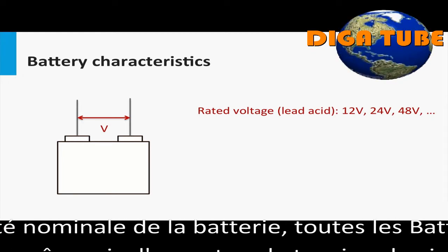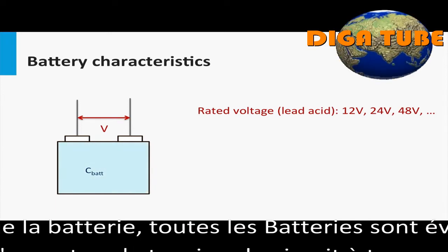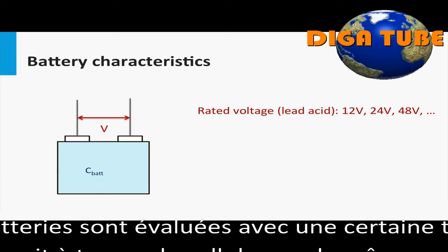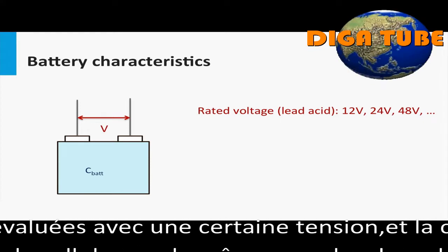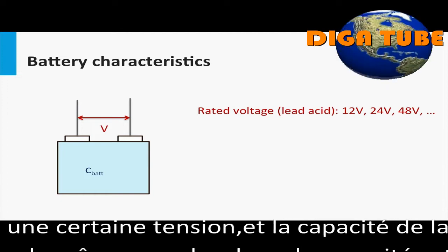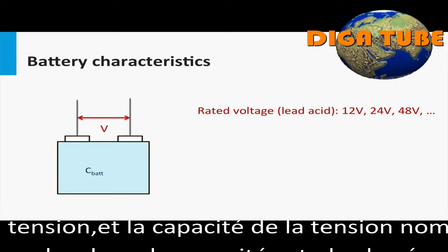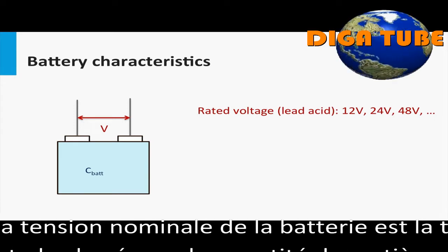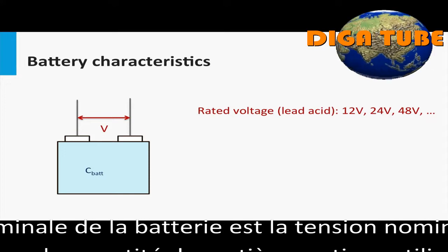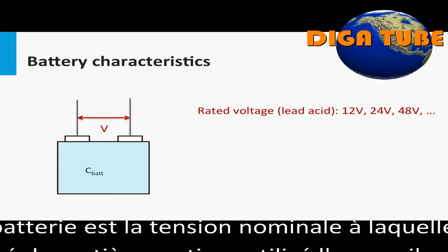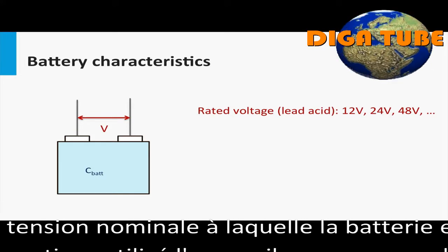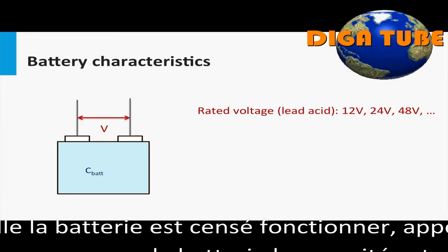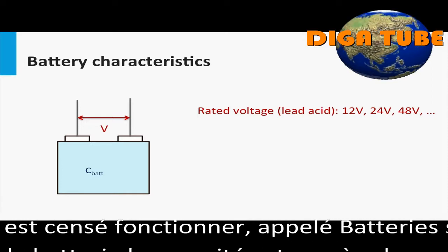at the system level. The term capacity in the domain of batteries refers to the amount of charge that the battery can deliver at the rated voltage. The capacity is directly proportional to the amount of electrode material in the battery. This explains why a small cell has lesser capacity than a large cell based on the same chemistry, even though the open circuit voltage across the cell will be the same for both the cells.